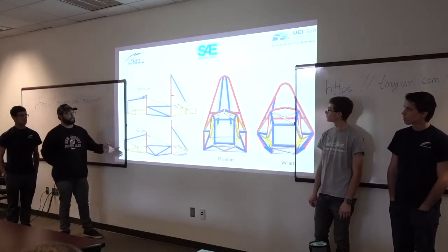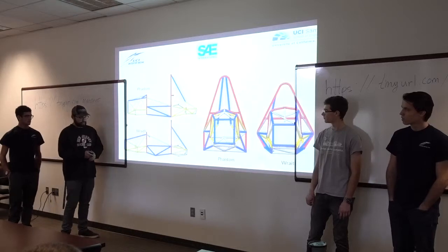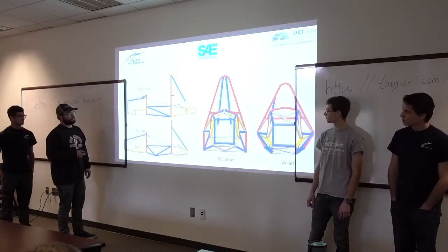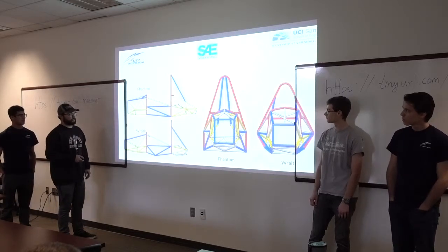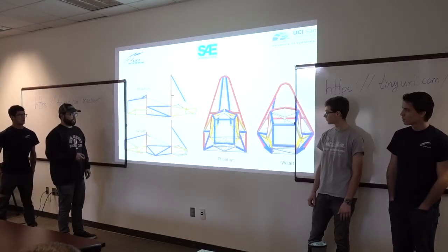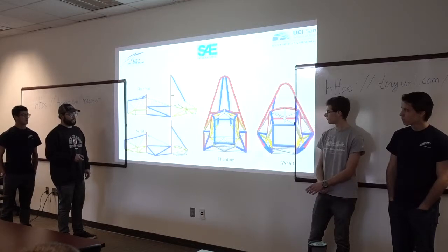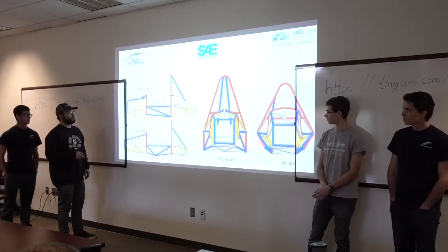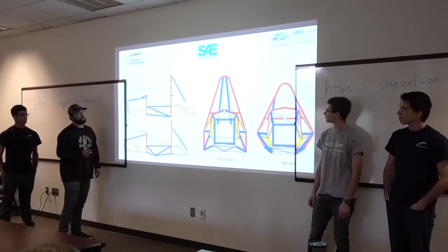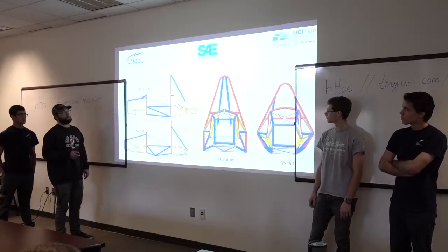So here's last year's chassis and this year's chassis. As you can see, we have completely eliminated the suspension box in this year's chassis by running our suspension nodes to this 1-inch 095, this is the main roll hoop, and to nodes that are loaded into the engine. We've also reduced the size of the main roll hoop by lowering the driver.